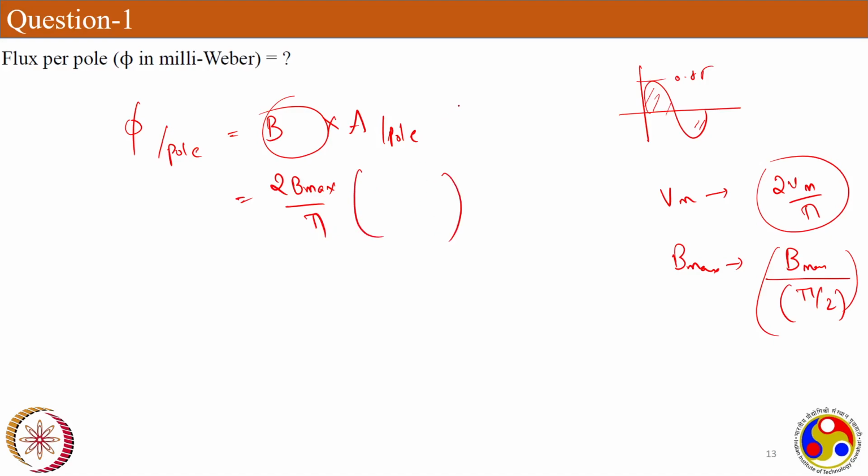If you need to calculate the pole shoe area, you have the shoe, and they gave you the diameter, and this is the length, and what is the area? Pi d L, right? So that's the area of the pole shoe. Two times B max.